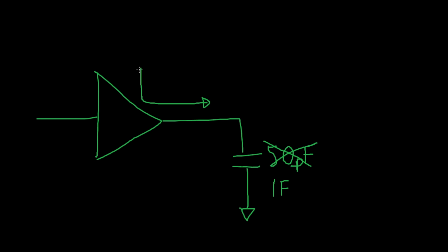And the fact is that you're going to end up in saturation for far longer than this MOSFET can handle. Typically, you're only going to want your MOSFET to be in saturation region and driving a lot of current for a couple of nanoseconds max. In this case, we're looking at 10, 20, 30 seconds to be able to charge up that capacitor, and that's most likely going to result in our MOSFET overheating and melting.